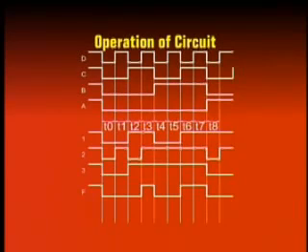At interval T6, the input ABCD to the circuit is 0, 1, 1, 0. The outputs of OR gates 1, 2 and 3 are all ones. The output F is 1, indicating adjacent ones.